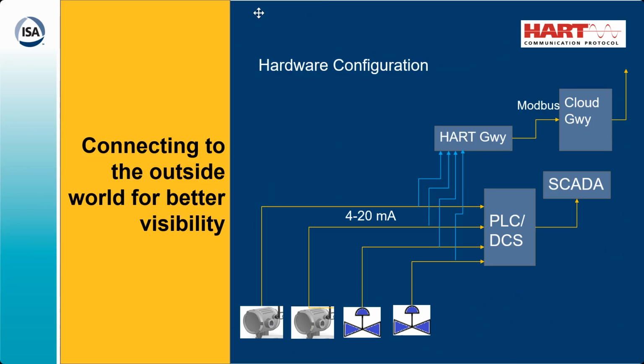That's right. And once you have the HART gateway, adding on the Modbus, are any additional efforts to be taken, how to go about that? Because that is the core of today's session or seminar. It depends on what kind of analytics you want to build, because you get a lot of data on the Modbus from the HART gateway.